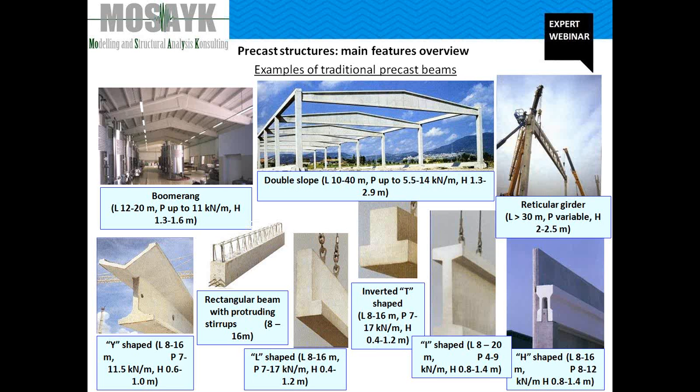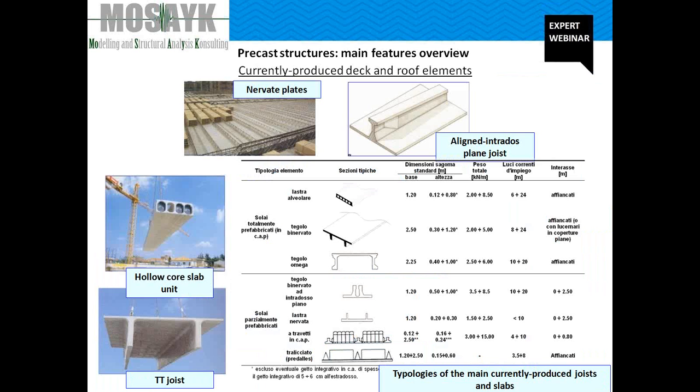Change means that it increases the period of vibration. This fact will probably reduce forces, but unfortunately it will for sure increase displacement. And we know that seismic design is more a displacement-based performance design and not a force design.